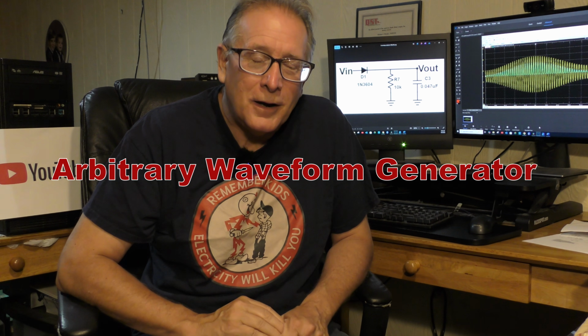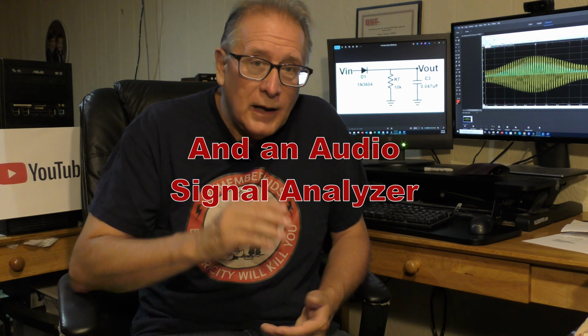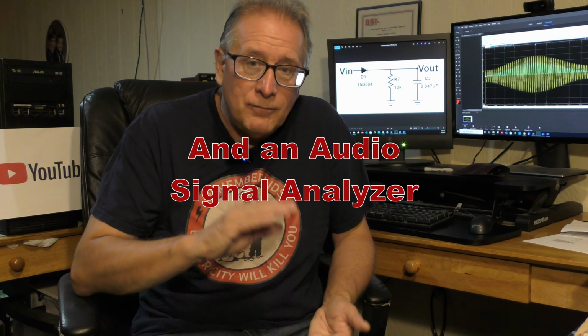To get an answer, we're going to have to look at the math, and the math tells us that an envelope detector is a low distortion type detector all the way up to high modulation indexes. However, the product detector version of AM demodulation, you start to see distortion creep in much after 30%, 40%. The distortion will creep up. So I've been able to get my hands on an arbitrary waveform generator where I can make an almost perfect AM signal.